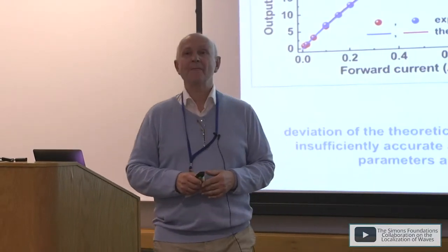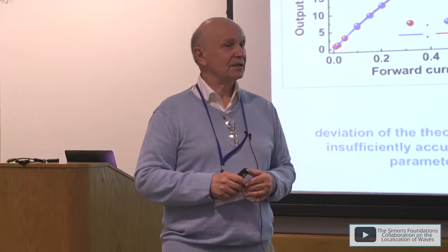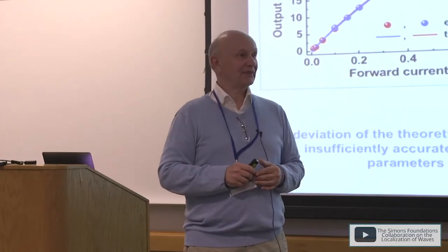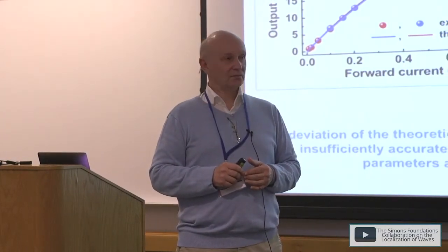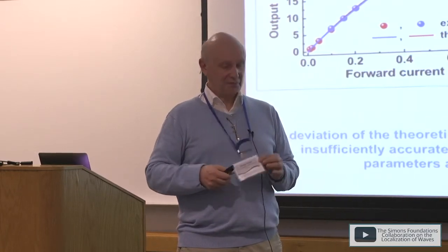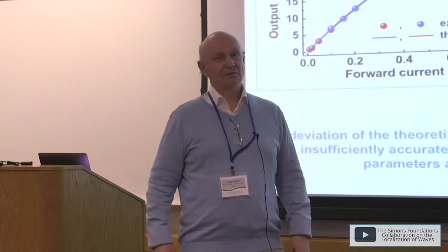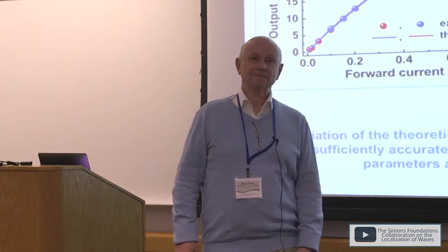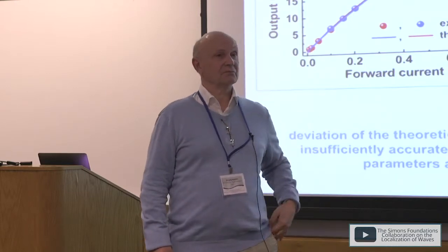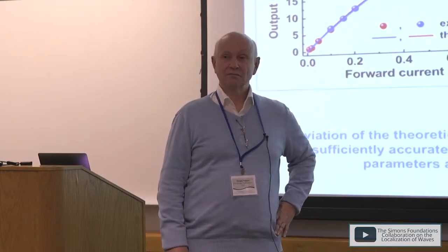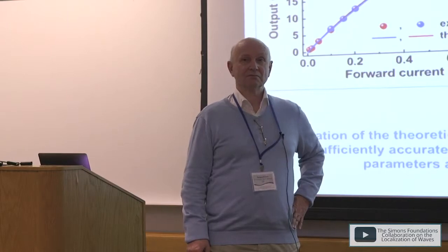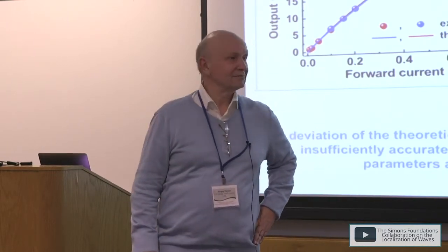Okay, let me continue on your thermoelectric question. You can have thermoelectric pumping in LEDs. Because if you bias at a voltage which is smaller than the emitted photon energy, you are supplying for each electron hole pair an energy smaller than the photon which goes out. And still you have emitted photons because you have thermal energy coming from the lattice, which brings up the electron and hole, and so you are cooling the lattice. This is a huge area of research, because you will get cooling by just emitting light out. So it's a good question. It can happen, but this is at low current.